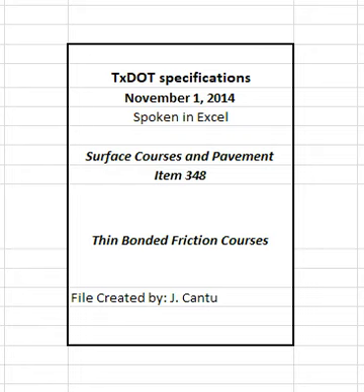4.4.2 Job Mix Formula Approval. The job mix formula, JMF, is the combined aggregate gradation, design level, and target asphalt percentage used to establish target values for hot mix production. JMF1 is the original laboratory mixture design used to produce the trial batch.